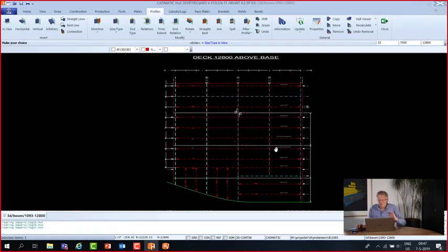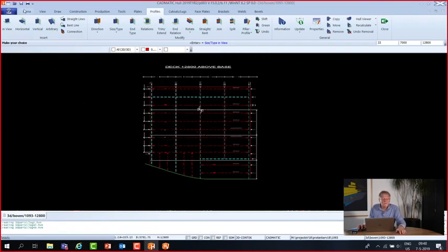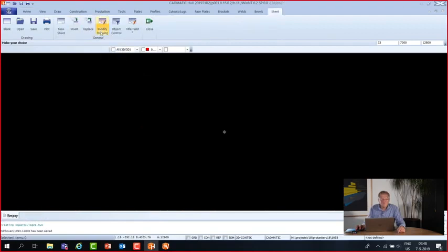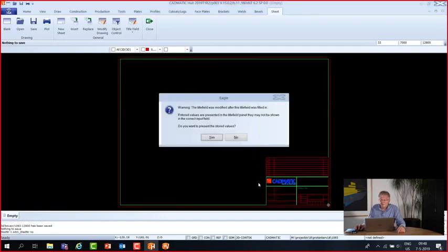Maybe something quite different in between. That's about the drawing, how to create a drawing, because that's one of the end products of the modeling. So we have this sheet button here, so I will touch this one and I will create a new sheet. You can select the right size. I think I want to have A2 if I'm right, yes. Scale 1:50, and the title field is displayed.